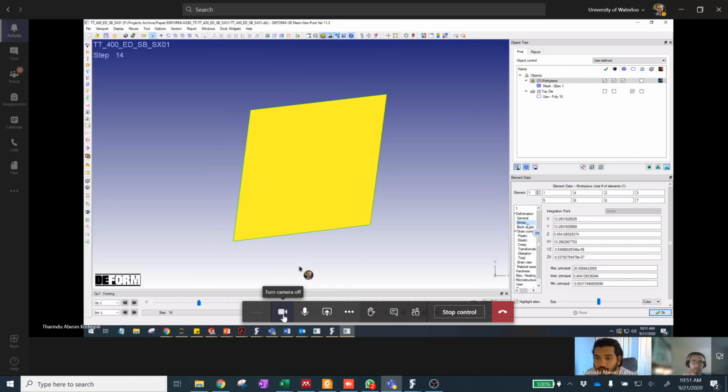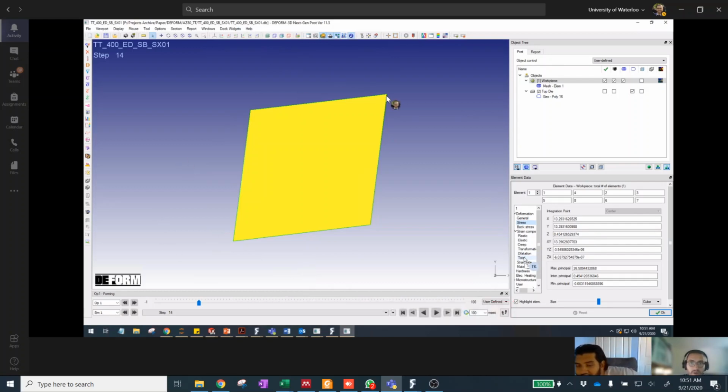So for this one, now we're looking at the stress. This makes way more sense because you have X and Y stresses induced and basically nothing in the Z, and they're equal in the X and Y direction. If you think about pulling like that, you're pulling this one corner, what is going to happen to the side lengths here and here? Are they getting longer or shorter? When you make it a parallelogram like that, these will get slightly longer, meaning that you have a tensile induced stress, and there's nothing in the through thickness direction, or virtually nothing. So that kind of makes sense so far.